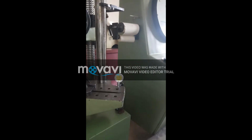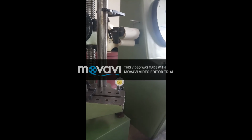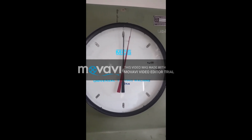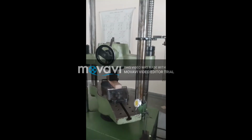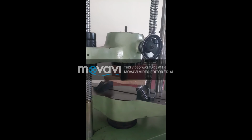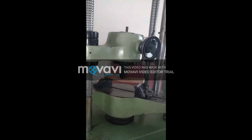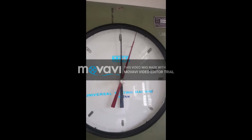This is the dial gauge, which you can observe. It measures the deflection or the deformation. From the dial indicator we take the value of the load. The load is commonly up to 40 kilonewton, and you can observe the material breaking, and finally the material breaks. After that we take the final reading. This is the final reading, and you can note down the values.